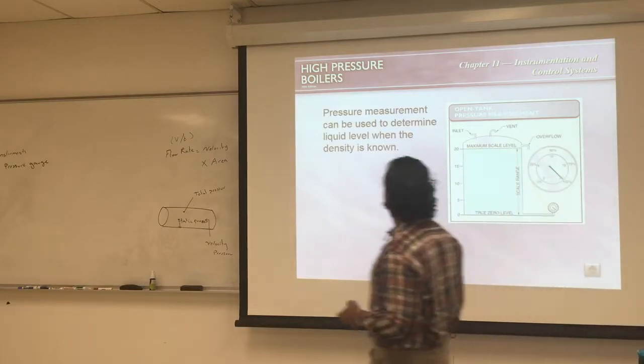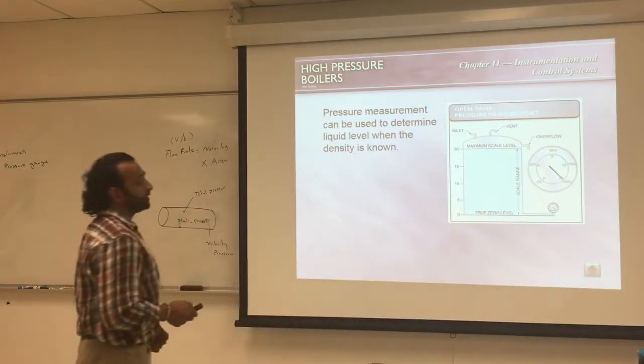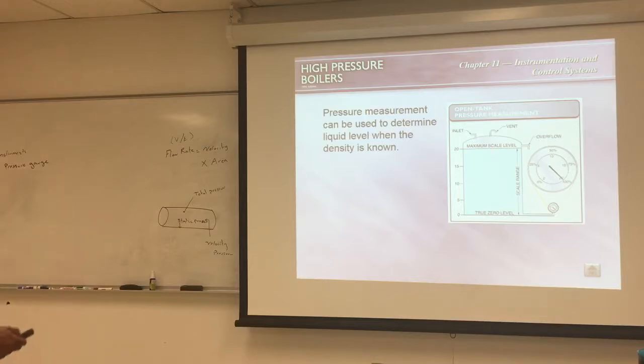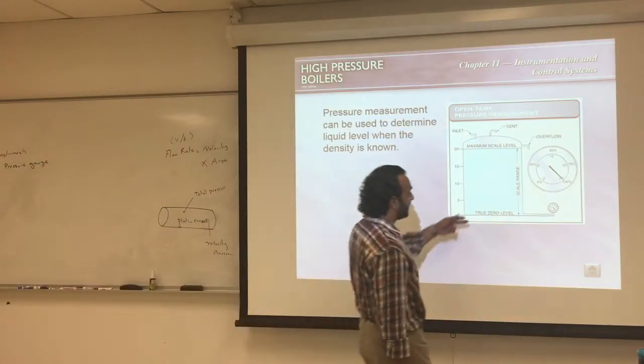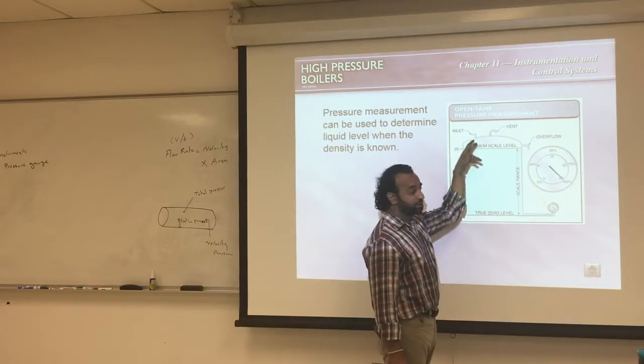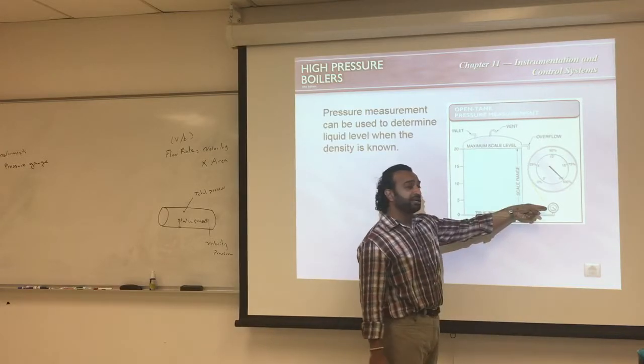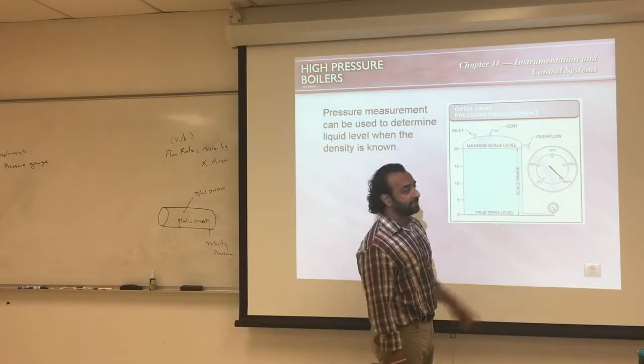Pressure measurement, again, same thing. Some of them we can combine with pressure to know the fluid level. We talked about that in week 4, and we said that the height of the water determines the pressure. So we can use pressure gauges to determine the water level inside the tank.